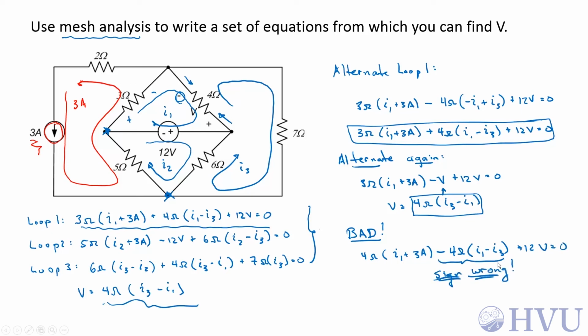We've started out with one voltage convention, that we're entering the negative terminal, but then we forgot about that when we decided what the voltage actually was across that element. Don't do this. Pick a sign convention, stick to it, and you'll be fine.